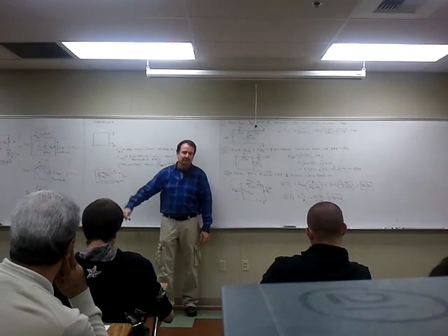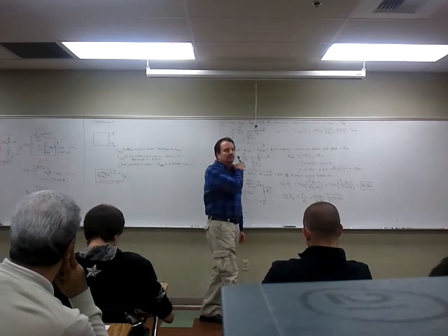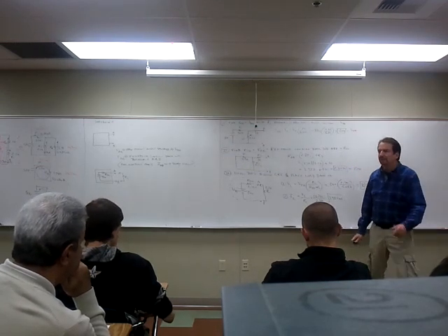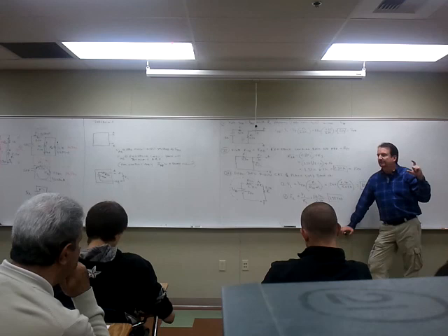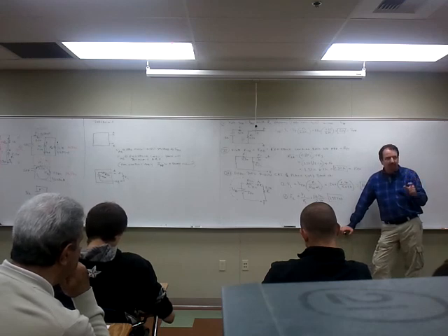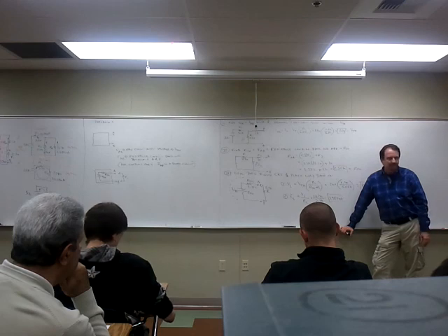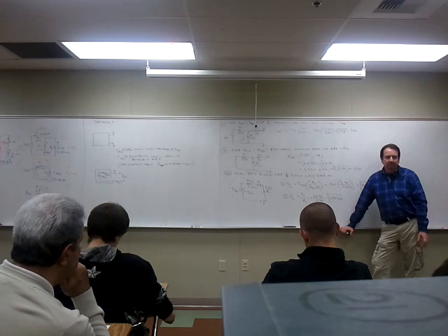So that's one reason. And the other reason, what was it? When we have a circuit where a resistor makes it complex, the very act of removing a resistor may make the circuit solvable. That bridge is an example of that. Before we removed that center resistor, you did not have a methodology to solve it other than 3 simultaneous equations and mesh, which is a complex analysis. But once you remove that resistor, it's a simple circuit to evaluate.